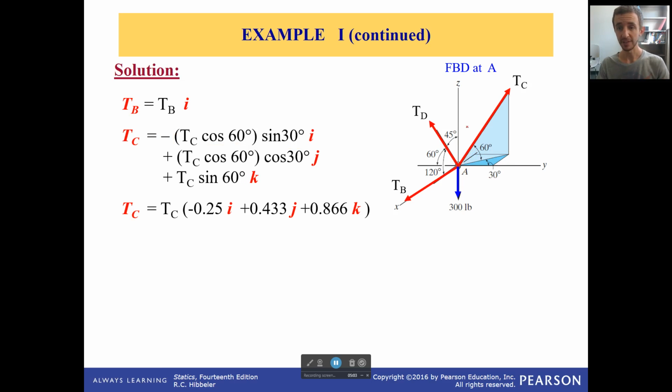Now, the second one is actually much simpler. We have this right here, and it gives us angles to all the axes, which means we can use those awesome angle cosines. The one thing we have to be very careful about, though, is with our y-axis right here. Because we don't use the angle from the negative axis, we always use the angle from the positive axis. Or you just have to be very careful with your sign. So in this case, I'm going to be very careful with my sign and say cosine of 120.